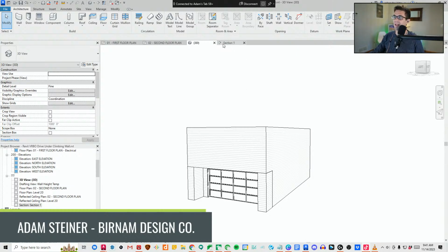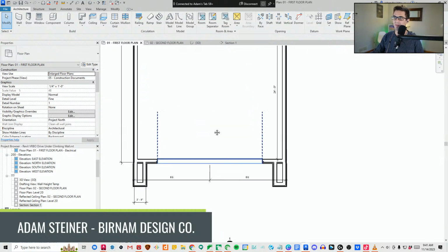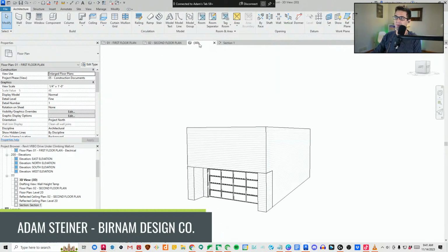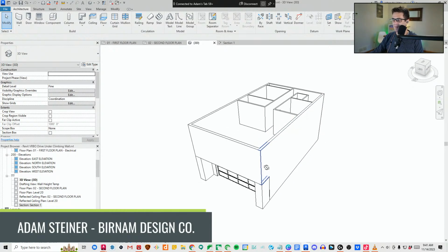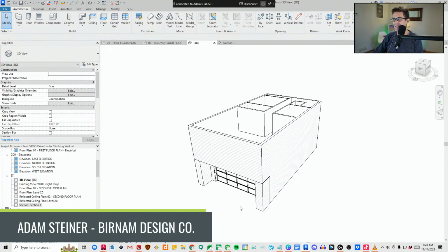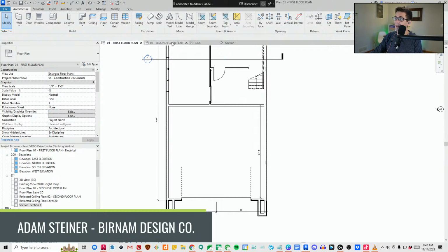Yeah, I've used the align command a ton. Yeah, so back to the differences in difficulty, Revit versus AutoCAD. It's probably the best feature of Revit that it models the building as you're drawing in 2 dimensions. But it's also what makes it the hardest because you have to think about all the ramifications. Like if you draw a line in AutoCAD, it's a line. If you want to make it a wall, you just call it a wall. It's not doing anything else to anywhere else in your model. But in Revit, if you draw a wall, it's going to put a wall somewhere in the model. And then there's joining and constraining and all that stuff that goes on. And you really need to think through it all.